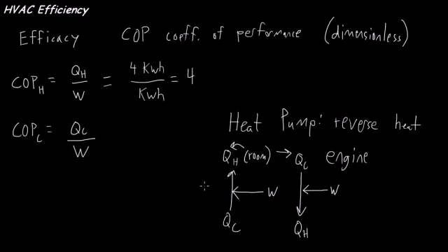So in cold climates, heat pumps don't work for the lower temperatures, so supplemental heat through some other means needs to be supplied. How they perform also depends on other factors in the climate like humidity. So the important thing to remember, COP is dimensionless.